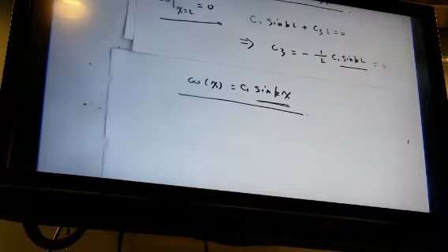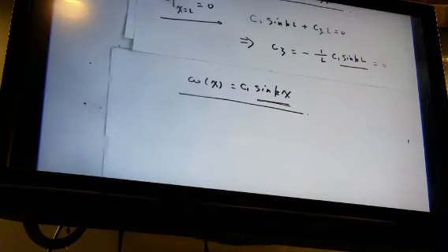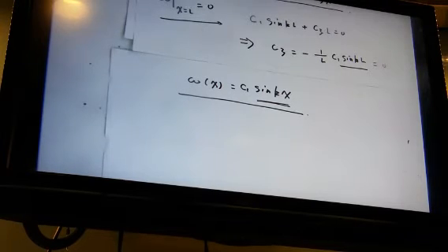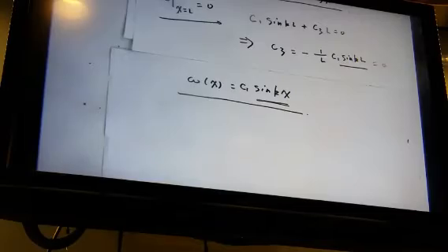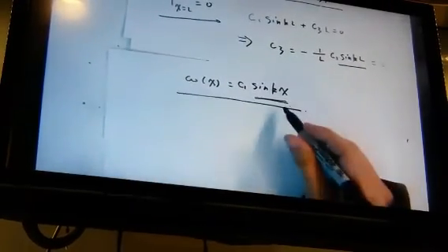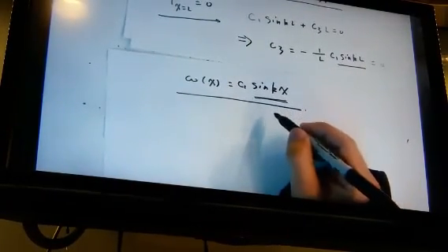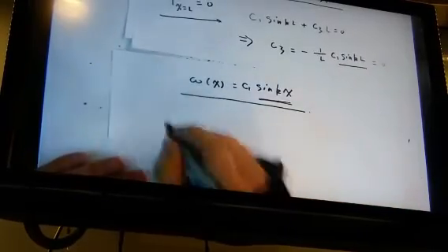You increase the loading, suddenly the material begins to flow like a liquid. So you don't know the deformed shape after that yielding point. That is so-called failure. Buckling is the same thing. You increase the load, suddenly it becomes unstable. We can predict the shape, but we cannot predict the magnitude. Okay? So C1 is the magnitude. Sine kx is the shape. What is the shape?